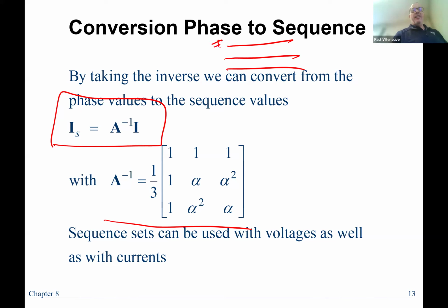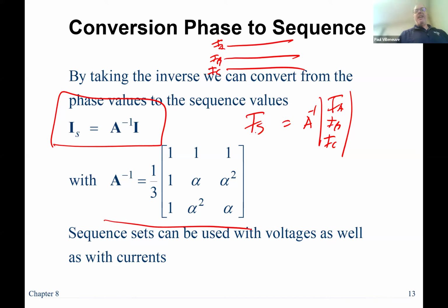This is phase A, this is phase B, and this is phase C. If I can measure those currents and stuff them in a matrix, then the relay can actually calculate all those symmetrical components.